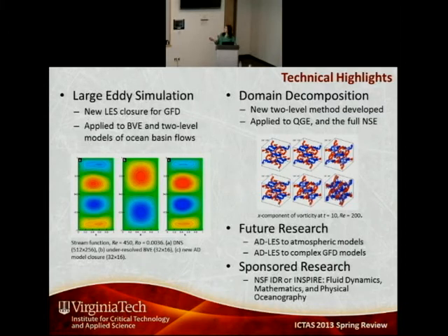Another technique that we had a lot of success with was domain decomposition. The basic idea is that in a lot of these fluid dynamics equations, you're solving an elliptic subproblem, a Laplace equation, to meet some condition at each time step. It turns out we discovered that if you solve this on a different grid, you can lower the resolution of the grid on which you solve the elliptic subproblem with no cost to the accuracy of the fine mesh flow field. You can actually reduce the second grid accuracy quite a bit.